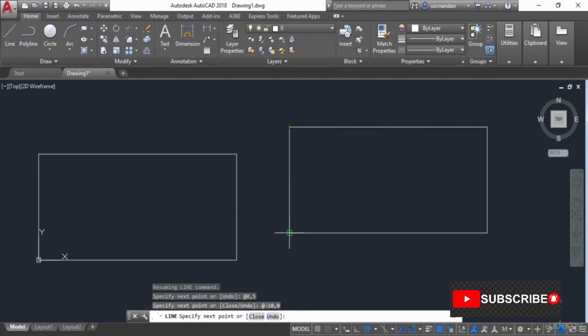Now we need to move to this point, and in this case we need to move downwards in the y axis, and the x axis value is 0. So let's type @0, -5, and press enter to return back to the origin, and press enter again.